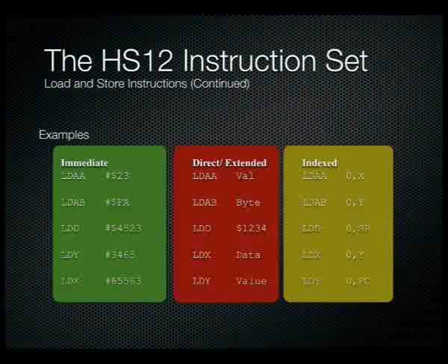If you want to use indexed addressing with respect to, in this case, the X register, you can simply go LDAA 0,X. So it will simply load the value out of memory that X refers to. And of course, I've given numerous other examples with accumulator B, accumulator D, and of course with the two index registers X and Y. So lots of different variations that we can use.